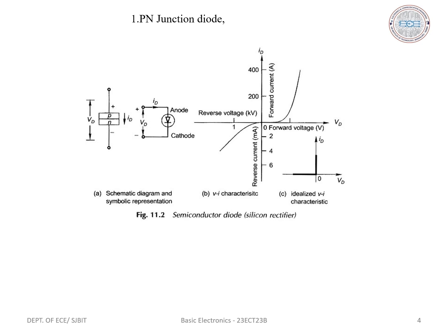When the depletion region collapses, a large number of majority carriers can cross the junction under the influence of the externally connected DC voltage. The large number of majority carriers crossing the junction constitute a current called the forward current. The current flow is of electrons, which is in the opposite direction to that of the conventional current. The forward current in a PN junction diode flows due to the majority carriers.